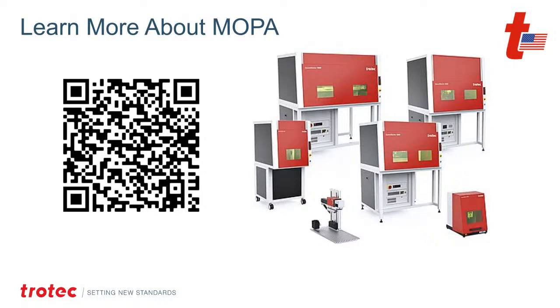They're both fiber. Everything a Mopa does, it's still going to do everything a standard fiber laser does, but it just has more capabilities, more control, especially when producing more colors on metals, and it'll also make your aluminums brighter white. It tends to do more darker colors on plastics and stuff like that. So it's a great alternative to a fiber laser, like a specialty fiber laser, if you will.